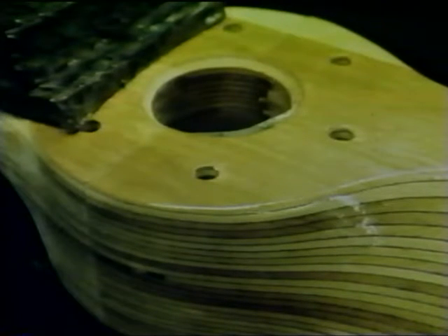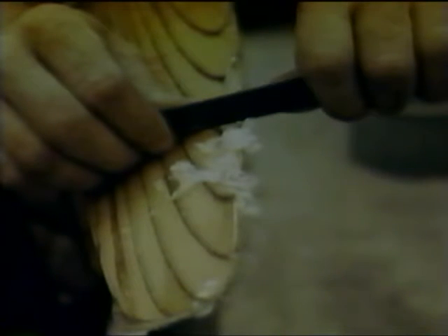After hand carving and balancing, a tough armor coating of nitrate plastic, approximately 30 thousandths of an inch thick, is applied to each propeller. This coating is applied to only one half of the propeller at a time. Each half is allowed to cure for 24 hours before the second half is put on. Lap joints, where both ends of the coating come together, are hand scraped to a smooth and beautifully finished surface.